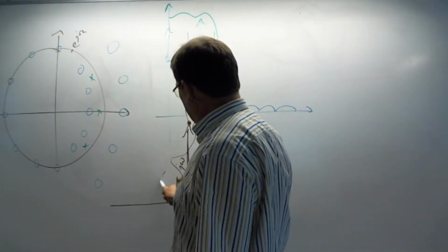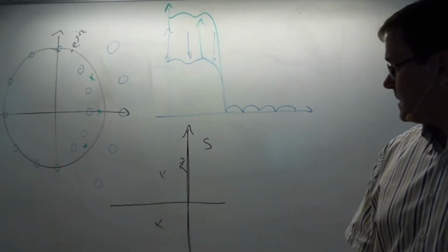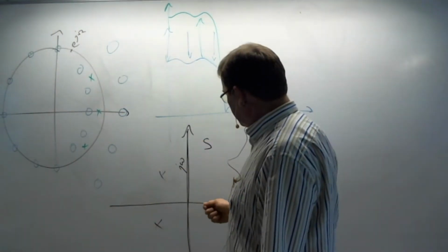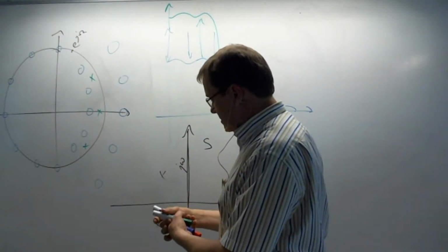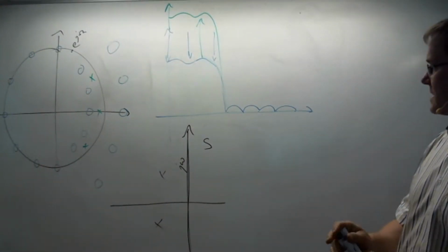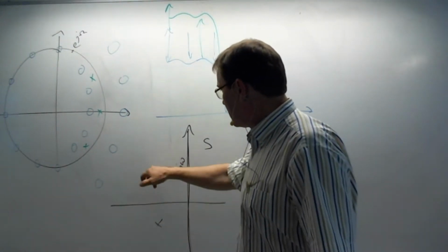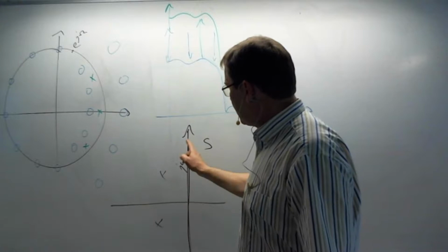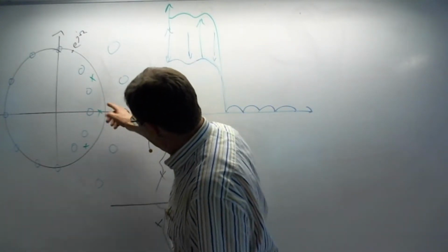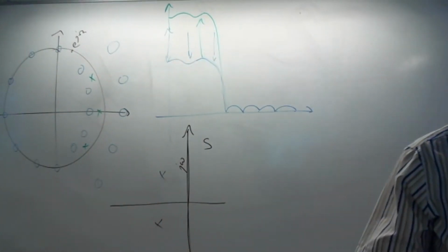Stable, and there we have the system, for example, like that. That will be Butterworth design. Basically, this bilinear transformation is the way to transform these pole locations, which are on the analog domain, in a certain way so that they actually fit into this Z plane.